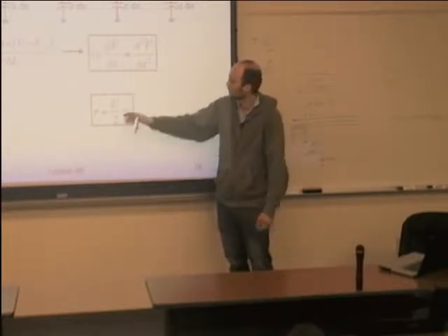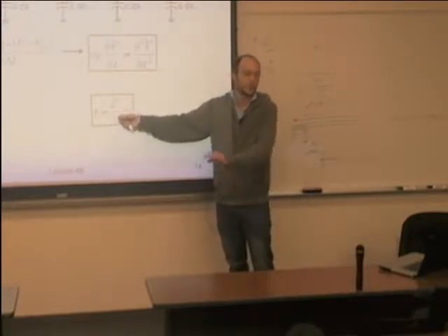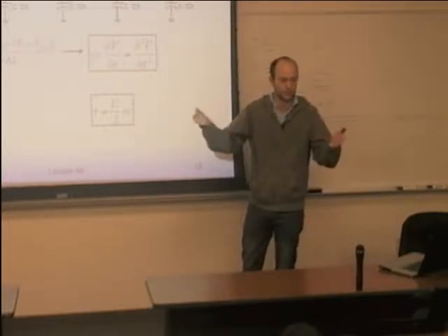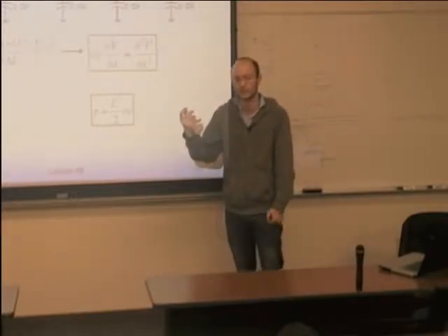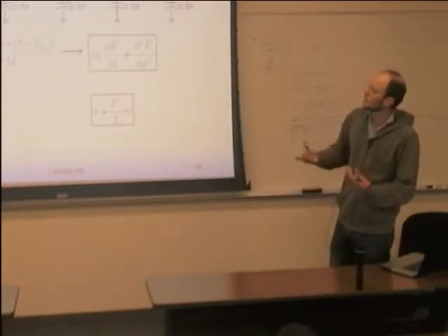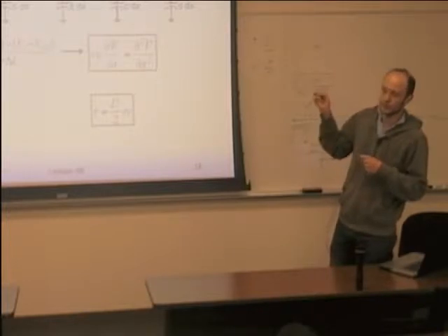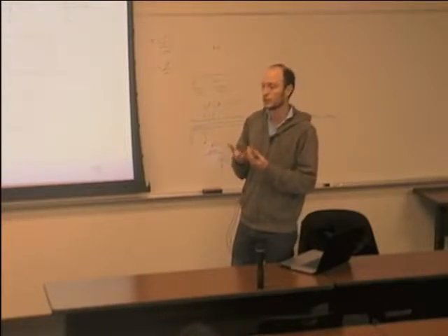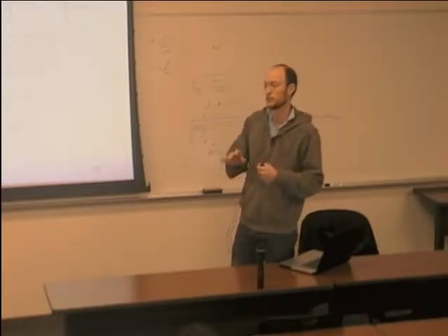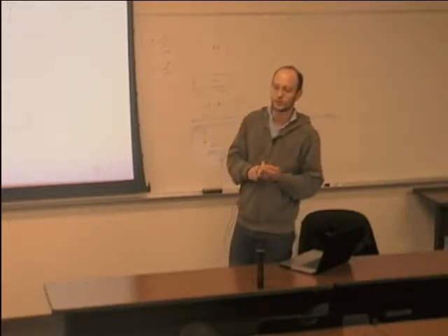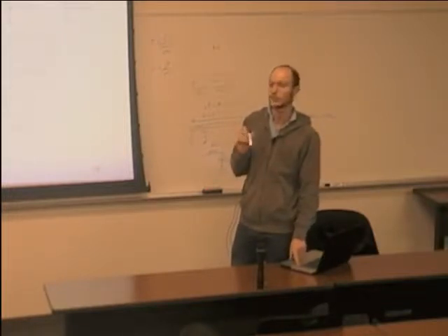So if there were not these two, probably no one would show this slide, because all they would tell you is that the wire just behaves as a resistor equal to the total resistance in series with a capacitor equal to the total capacitance. There would be no interesting effect. The interesting effect is that because of the distributed nature of the capacitance and the resistance, the effective RC product that you see is half of what it would be if you took all the resistance and all the capacitance and just put them as lumped elements. Does this make sense? Yes?